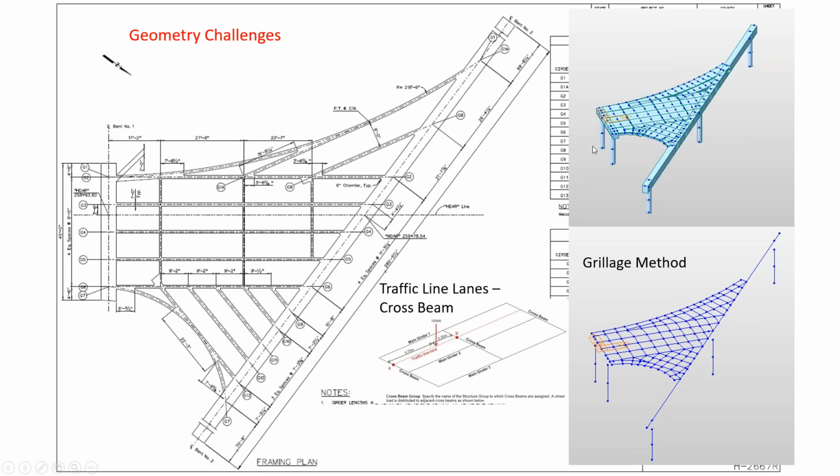For the live load, I can mention that this was not a very common bridge. I was not able to use the spine model for the bridge because of the irregularities in geometry. So I had to use the Grillage method, and the software that was available to me at that time was MIDAS. It was in 2015. There are some conditions about how to apply the live load in the Grillage method. I will talk about that later.